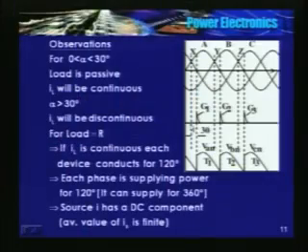It's possible, fine, till you trigger the gate of T1, it's blocking. So the only difference is you can have a positive voltage appearing across a blocking thyristor. So beyond X, till you trigger T1, a positive voltage appears across it. The variation follows the same procedure, VAN minus VCN.